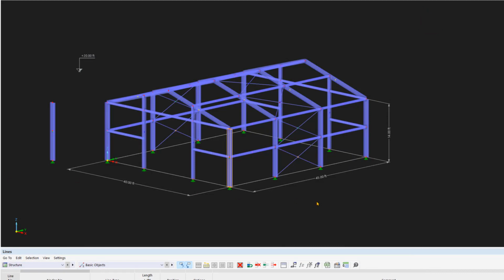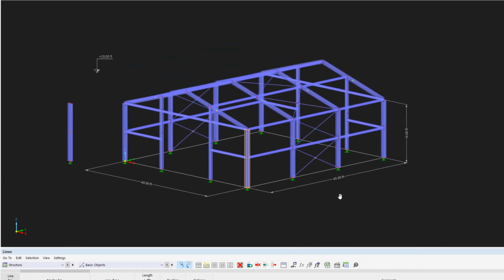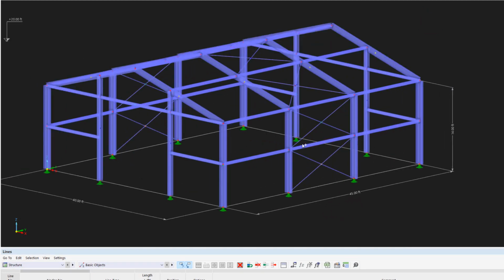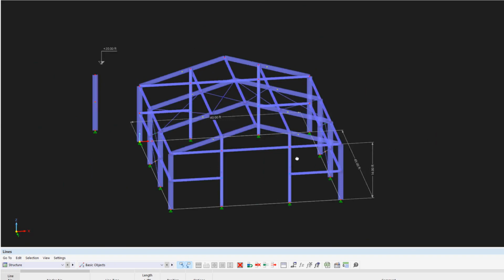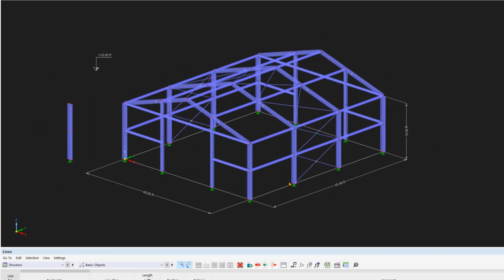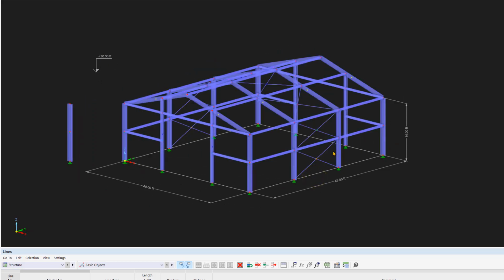By pressing the scroll wheel in, you can move the model back and forth. Holding down the Control key and pressing the scroll wheel in at the same time allows you to rotate the model. This is very similar to the cube. Rotating is also possible by moving the cursor while pressing the scroll wheel and right mouse button simultaneously.